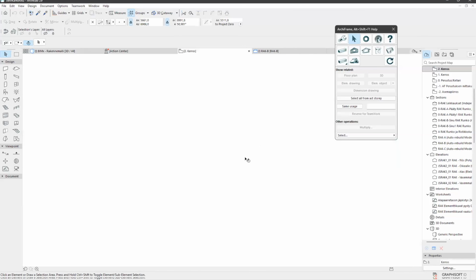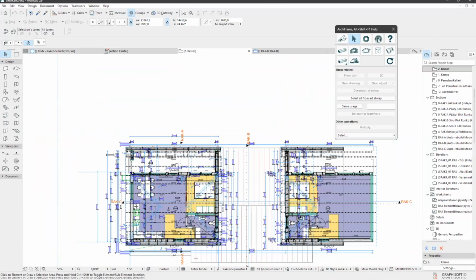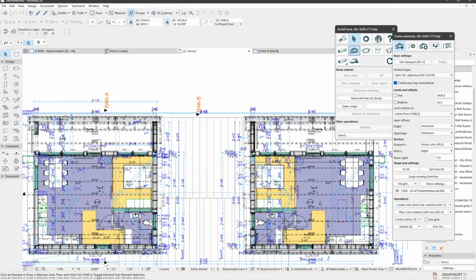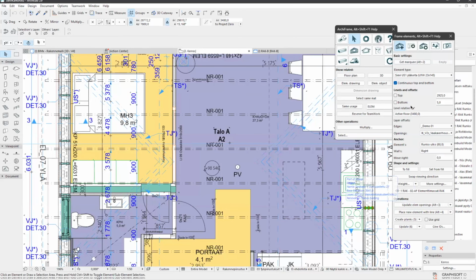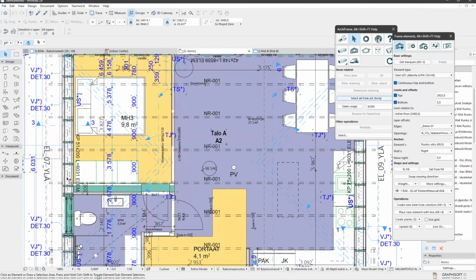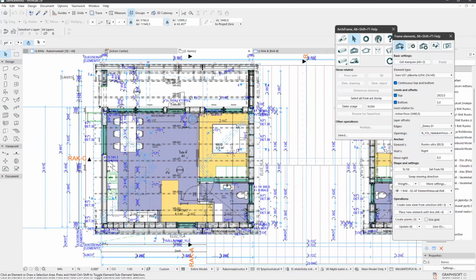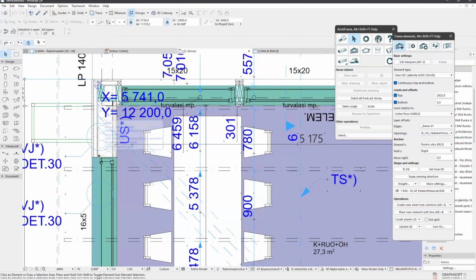And let's go to the floor plan. And here I'll take the element tools, cheat a bit, take the settings from an existing wall to get all these levels and settings to this palette. So I'm going to place the framing structure here to this wall that we hadn't made yet.